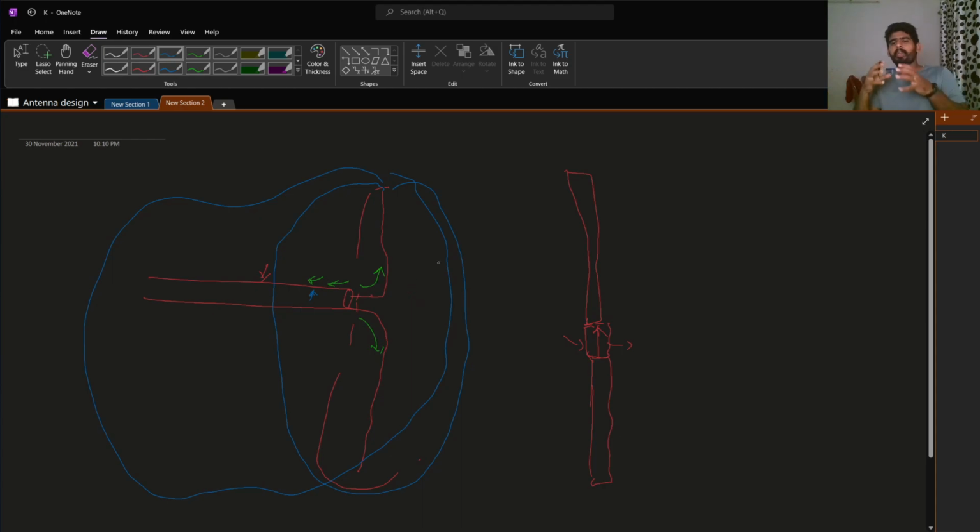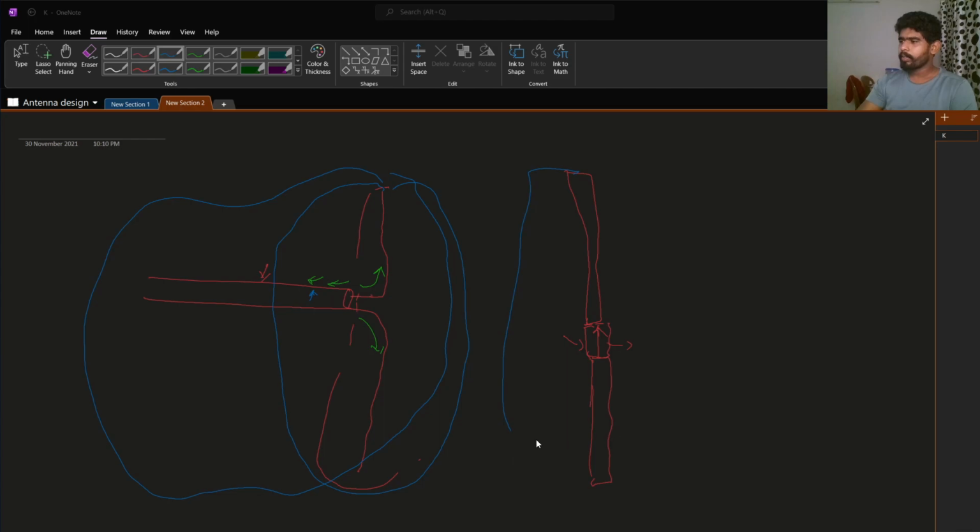You can easily identify this when you fabricate the antenna. When you place your hand close to this antenna, the performance of the antenna changes, the impedance of the antenna changes. So maybe some people directly conclude that the theory and the simulation are wrong. But the actual issue is how they simulated. The simulation is wrong here. They did not consider anything related to the modes. So that is the issue here actually.